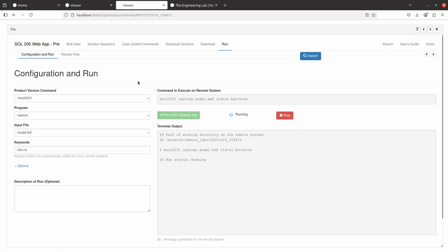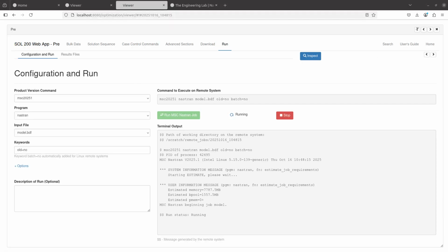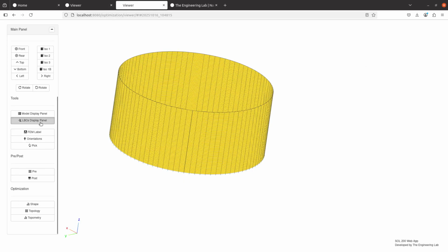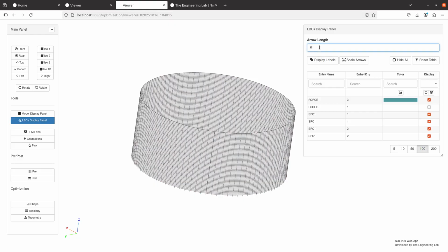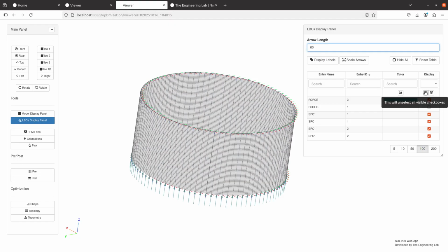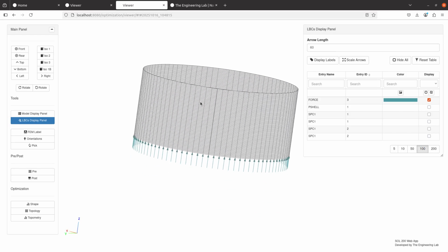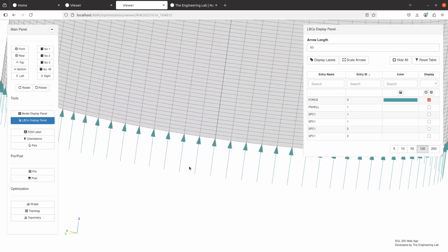So again, I want to take this to very high loading. And let me look at my notes here. Right, so you might be asking, where did I get the value of 10? Let me go ahead and show you the loads. So here's the axial loading. If you combine all of these, and then you find what scale factor gives you a million, you end up finding that it's 10.